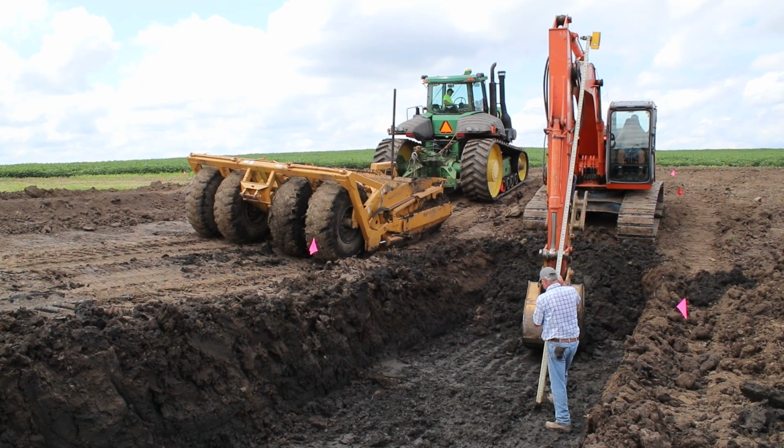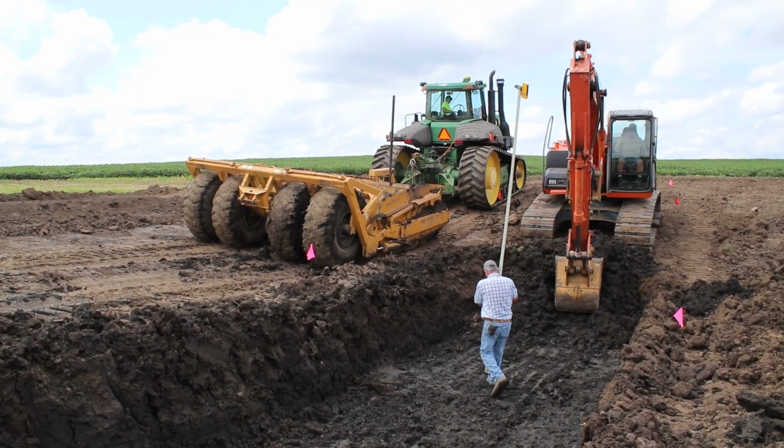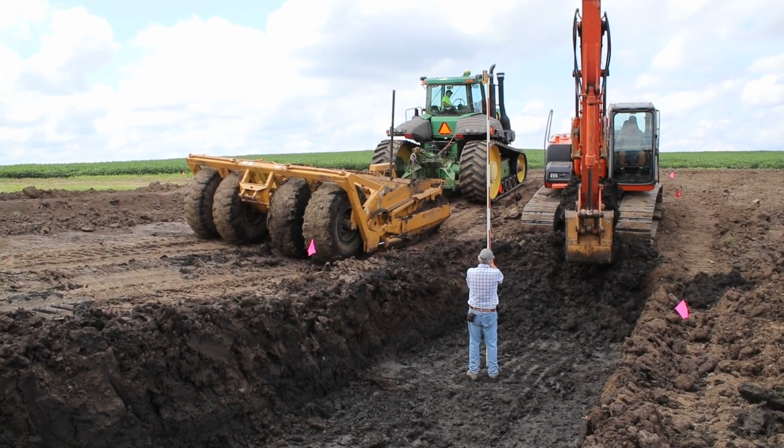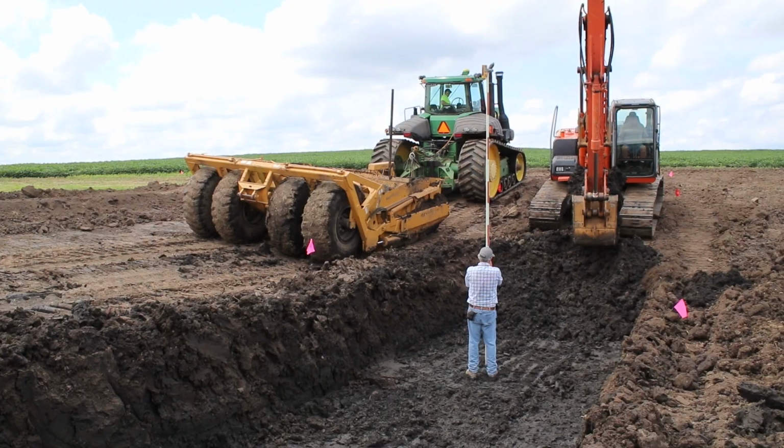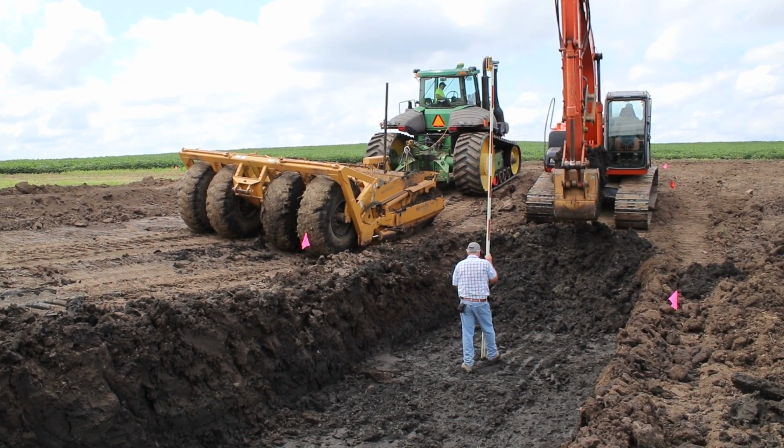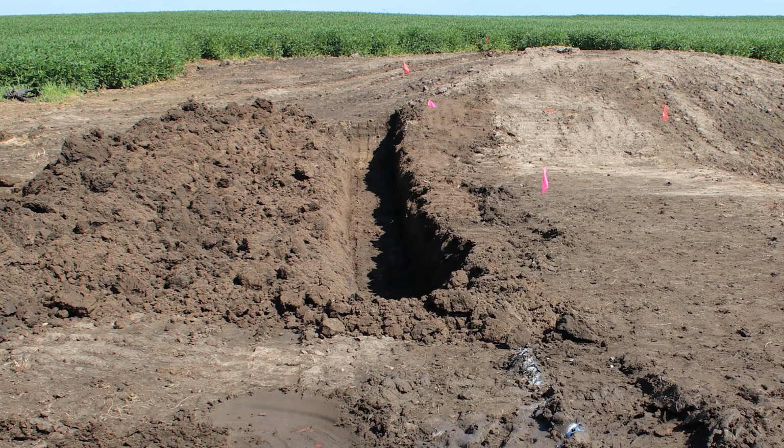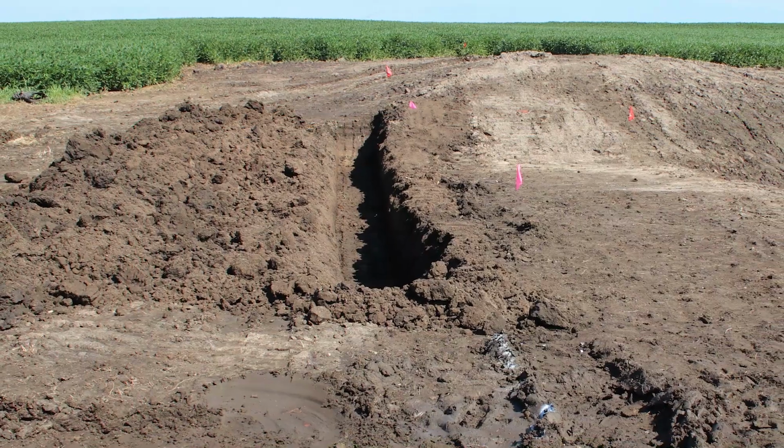With the rough grading completed, the contractor can now start working on the inlet apron and trench at the top of the chute slope and the outlet apron and trench at the bottom. The contractor excavated the area of the outlet apron, being sure to set the layout and depth to the location and elevation specified in the design. Meanwhile, a trench was dug for the inlet apron at the top of the slope.